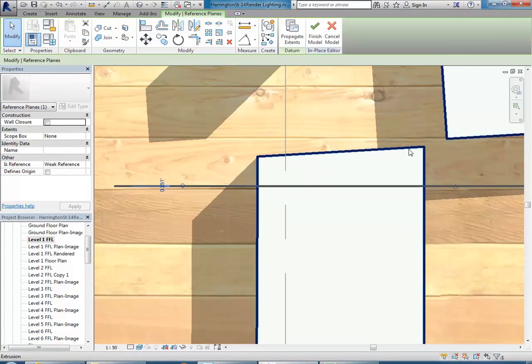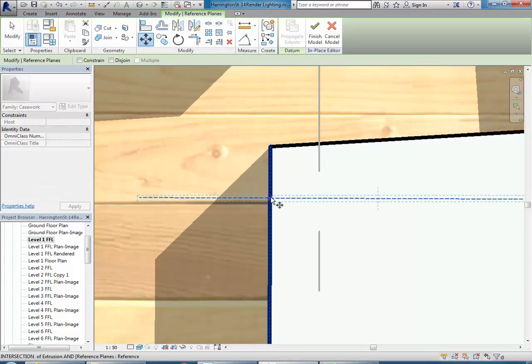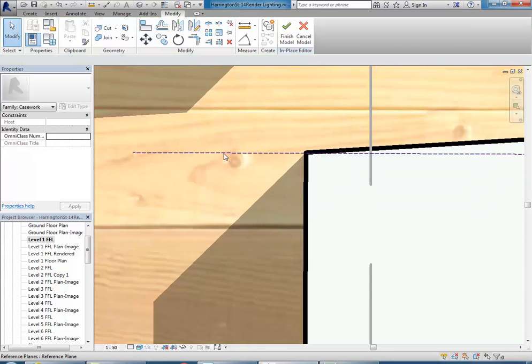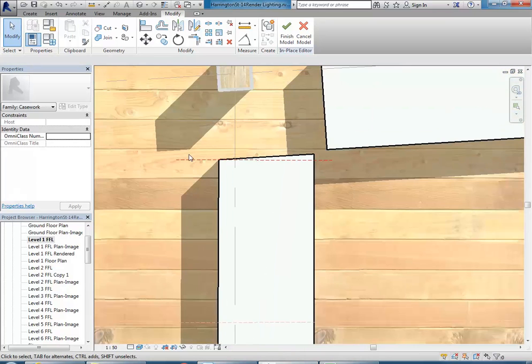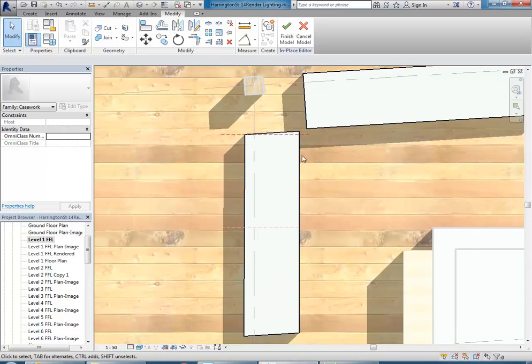But that edge wouldn't have been, so I would have had to rotate it, which you can do, but this is better. So there now I can move that plane to the corner. Right, so my cylinder, or my circle, the profile I'm using to make this cylinder, is going to sit on that surface and then be extruded down. Yeah, so it's just thinking in 3D, and it's almost like picking your drawing board up and putting it at different angles, so that you can project things in different directions.